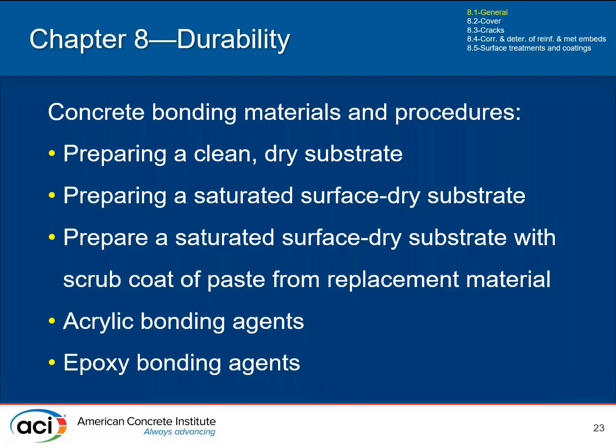It is touched on in other chapters, but it's also something you need to think about from a durability viewpoint. And these are just some of the different ways that can be used to achieve bond. Preparing your substrate correctly, having it saturated surface dry, using the scrub coat, using bonding agents. And I just do want to throw up a flag, from a personal experience viewpoint, something you should watch out for with bonding agents.